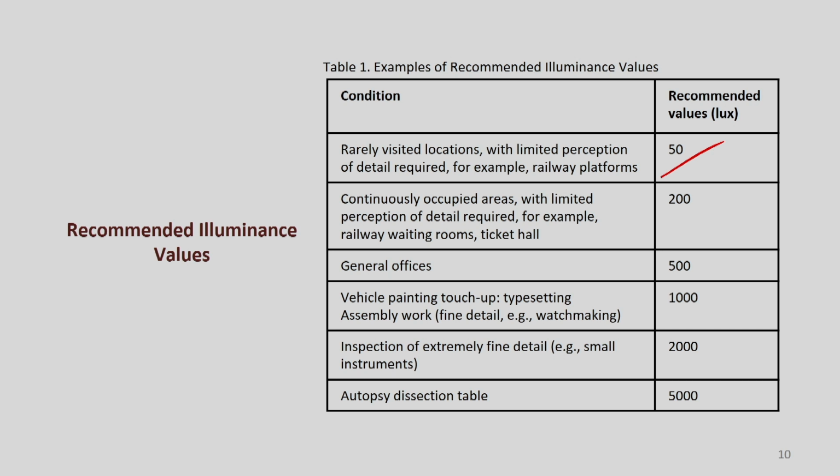But when we are talking about the office environment, where we have to read documents, answer something, do some critical job, in those cases it is 500 lux. As the criticality of the work environment keeps on increasing, the demand of light or demand of visual environment keeps on increasing.